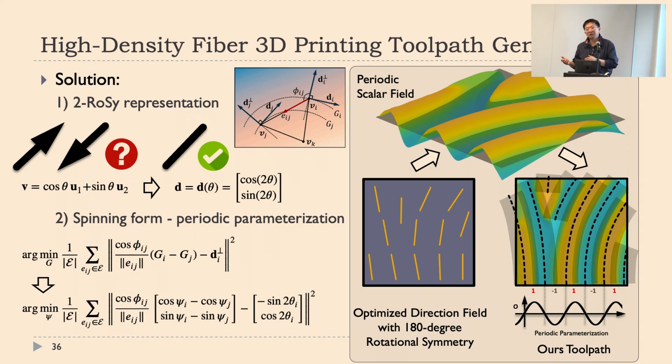The current solution is that we generate non-uniform layer thickness. We're using adaptive slicing, introducing more layers and even more partial layers, trying to solve that. But that is more like post-processing. Then we are looking for the opportunity to generate a direct solution, allowing certain partial layers to be represented by the scalar field.